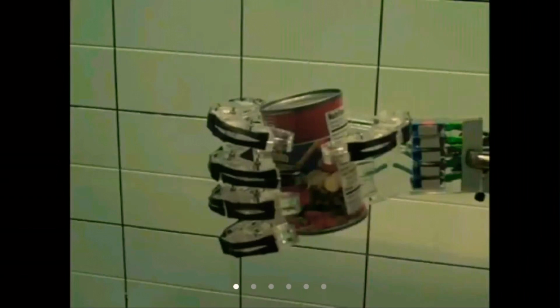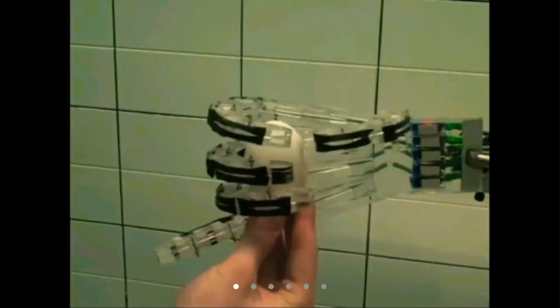Instead of using electrical motors, electromechanical actuators, we're using compressed air. We developed these novel actuators for the joints. So it's compliant. You can actually change the force simply by changing the air pressure, and it can actually crush an empty soda can. It can pick up very delicate objects like a raw egg, or in this case, a light bulb. The best part, it took only $200 to make the first prototype.